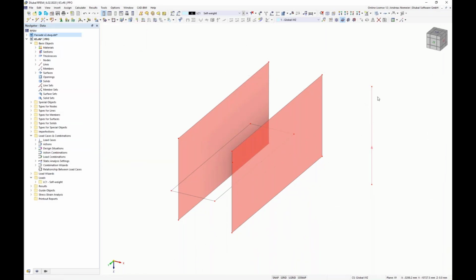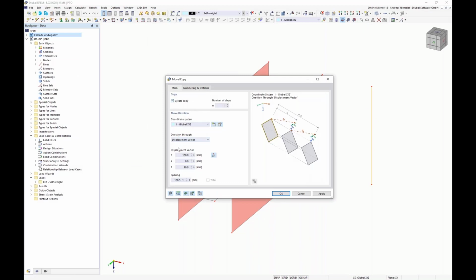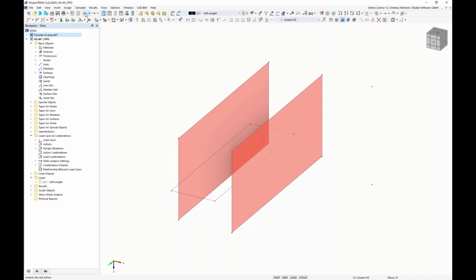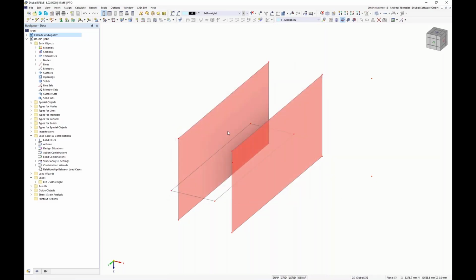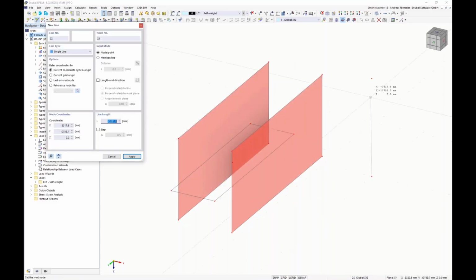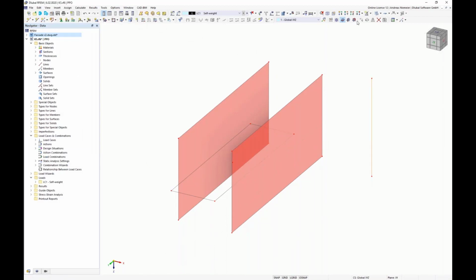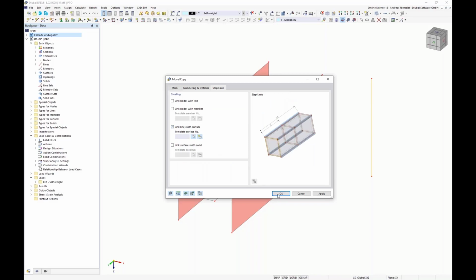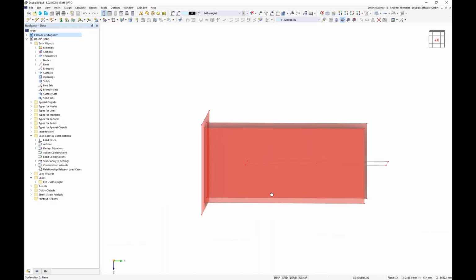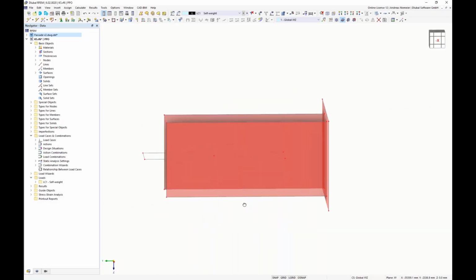and then we draw a new surface, create copy with, oh, I made an error, I think, again. This is 10 millimeters, I should remove. Okay, now we can make a line in between and draw a new surface by using the vector -200 millimeters, create copy, using step links with a new surface and connecting it. Then we have almost all elements done.